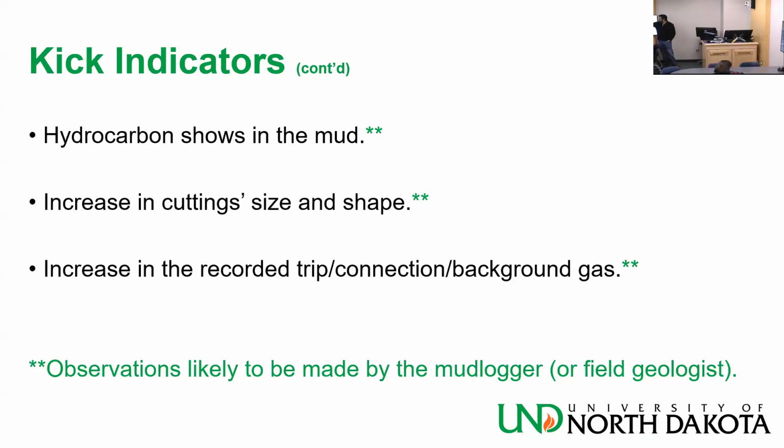Okay, hydrocarbon shows in the mud, an increase in cuttings size and shape. What is the problem with that is that the mud logger will notice that, but the mud logger doesn't work with the depth that the bit is at, or the depth of the well. He works with the lag depth, L-A-G. This is the depth that the mud coming out is coming from.